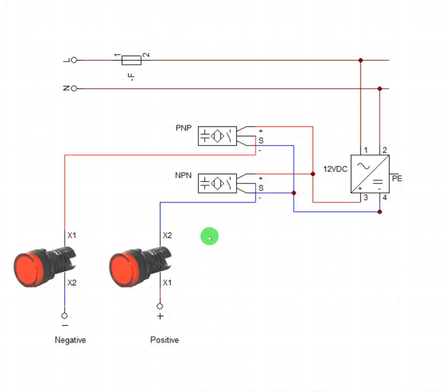That is what we call polarity. Polarity simply means positive must go to the positive terminal, and negative must go to the negative terminal. If you want to polarize a connection, you make sure you follow the sequence of connection. If you reverse them the other way, some systems might not work correctly. And that is strictly for DC signals. All right, so let's simulate for a short while.